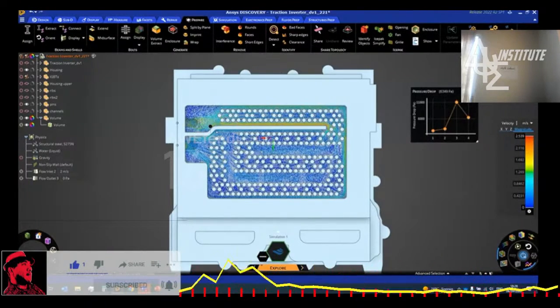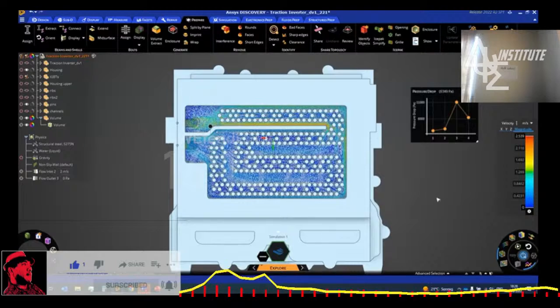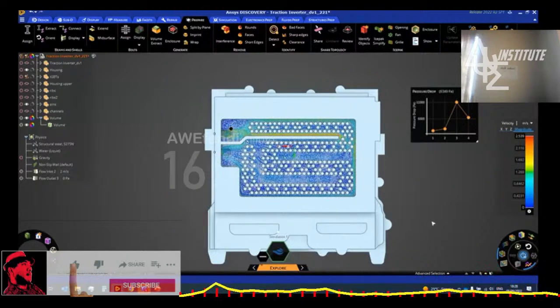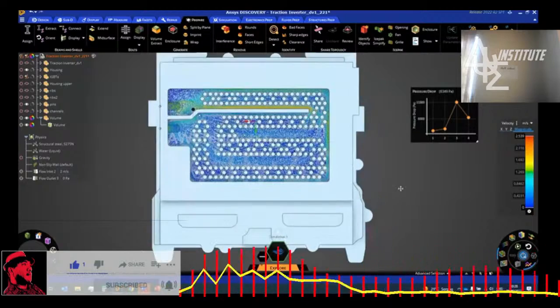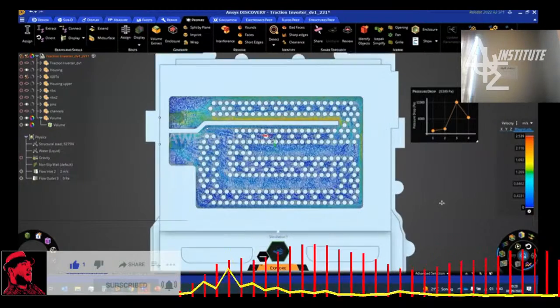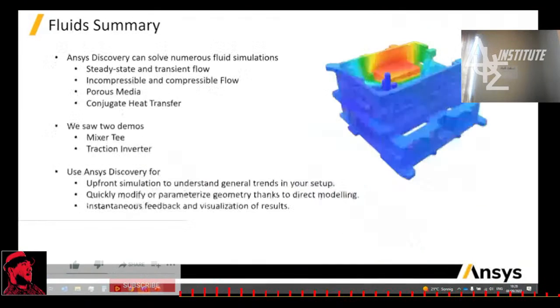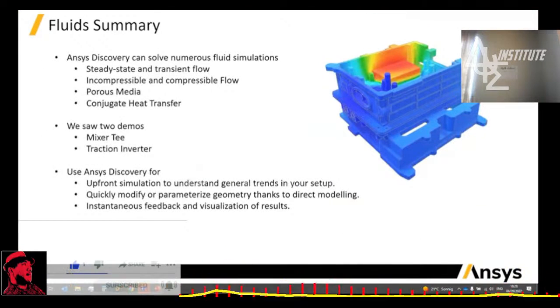So, to completely validate this afterwards, you would have to insert again the other solid components, the IGBTs, and do a full-blown CHT calculation to see the behavior of the full system. Let's go back to these slides. And this brings me to the end.